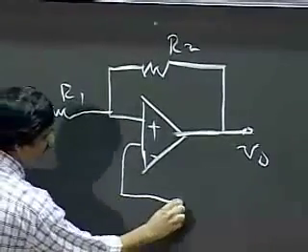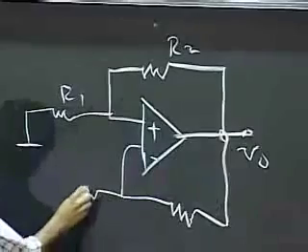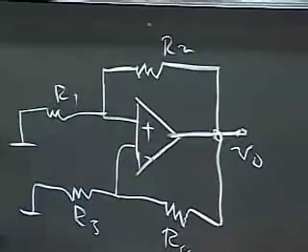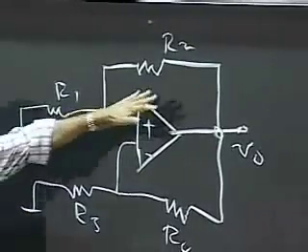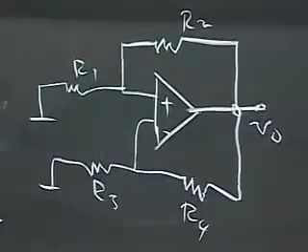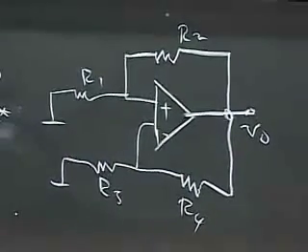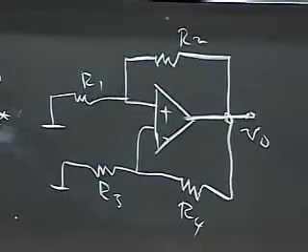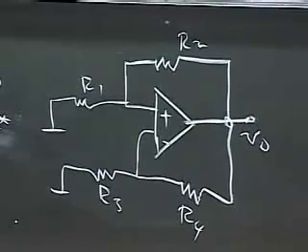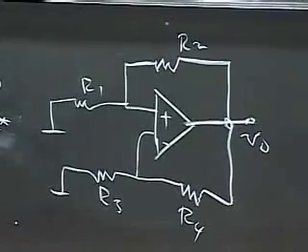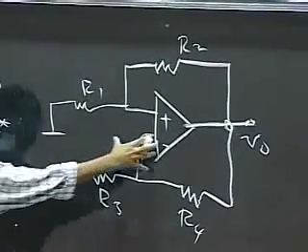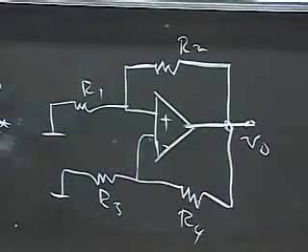And I'll do the same thing on this side. All I'm doing is applying both a positive feedback through R2 and R1 and negative feedback through R4 and R3 and representing the dynamics of the op-amp and then standing back and seeing what happens. So I'm sticking positive feedback, negative feedback, the dynamics of the op-amp here, and let's see what happens. What I'd like to do is impose this circuit on top of this op-amp model.